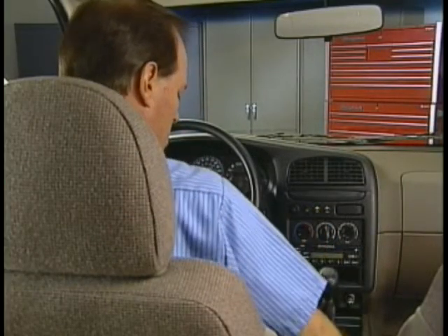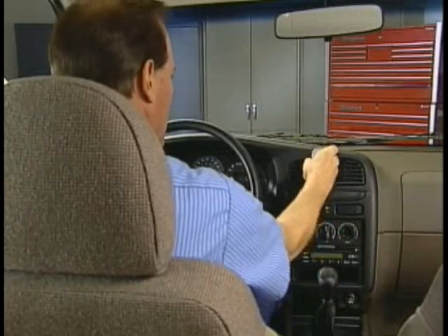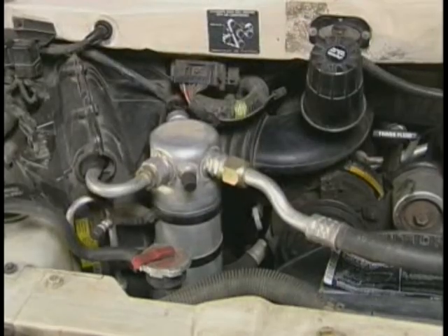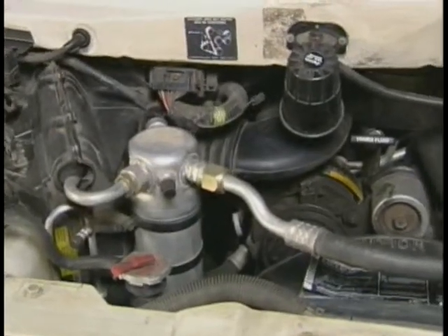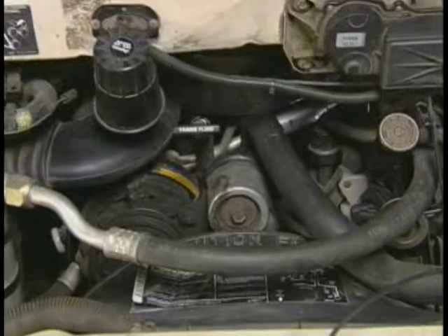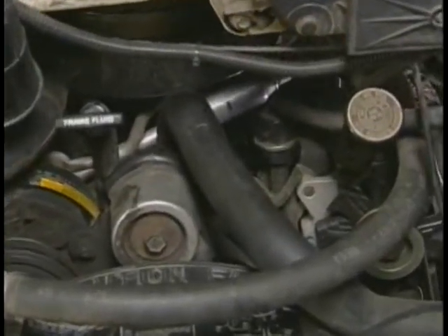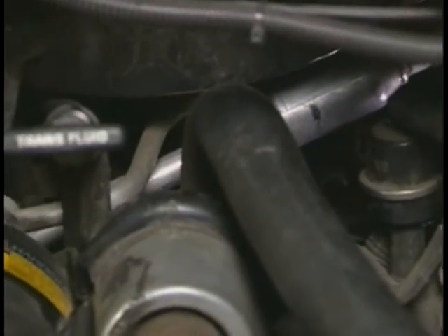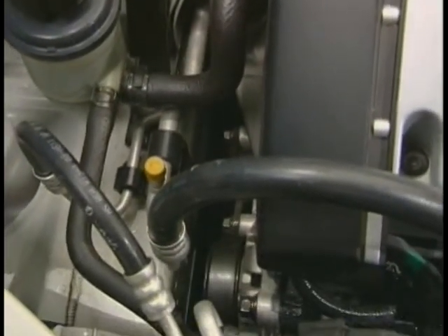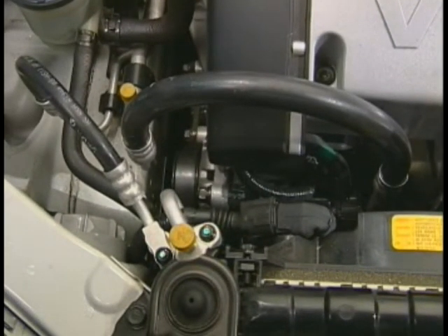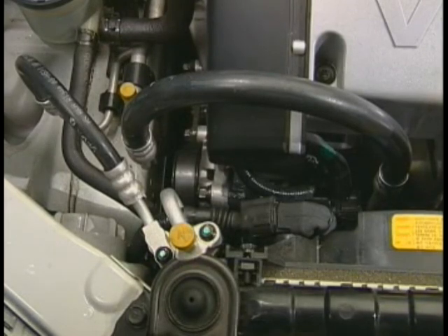Automotive air conditioning systems use the principles of heat, temperature, and pressure to cause the movement of heat from the passenger compartment to the outside air. The air conditioning system uses these principles to change the pressurized refrigerant in a system from a liquid to a gas and back to liquid, and in the process absorb and release heat. The air conditioner also uses the movement of pressure from an area of high pressure to an area of low pressure to operate. In an automotive air conditioning system, anytime there is a change in pressure, there is a change in temperature. During the pressure-temperature change, there is also a change of state from liquid to vapor or from vapor to liquid.